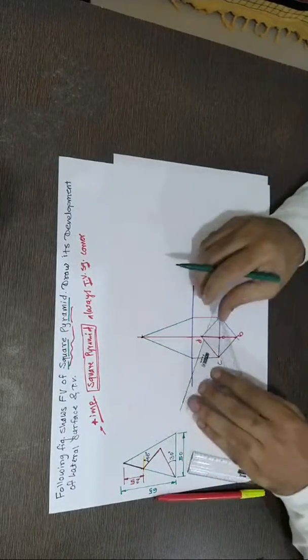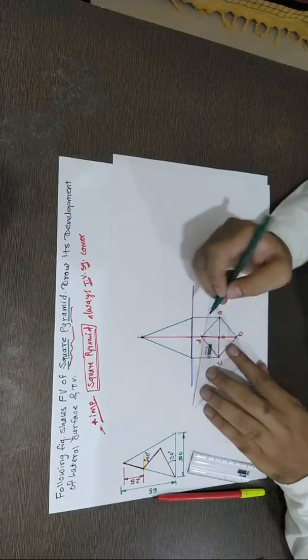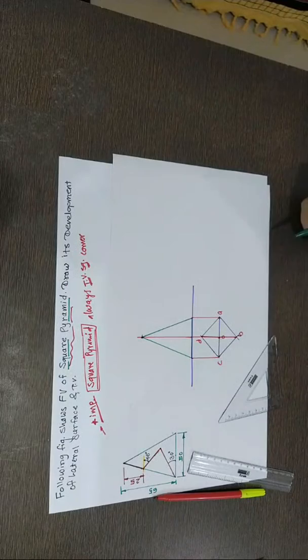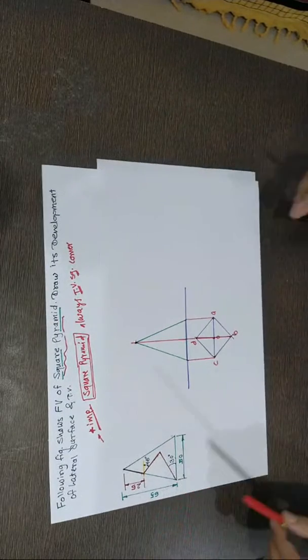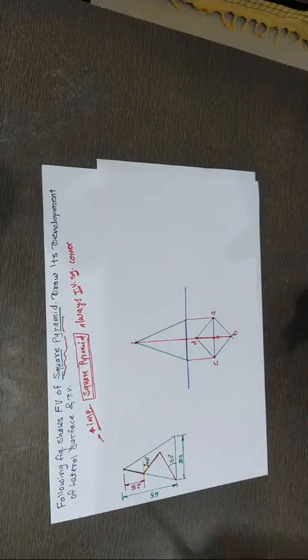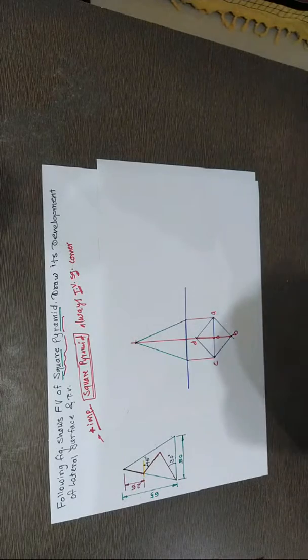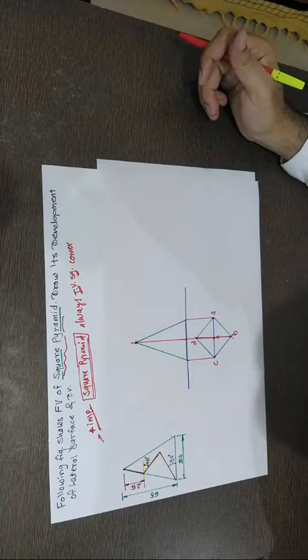So this makes it very easy and it makes the least mistakes. If you draw the square like this, or means resting on a side, there may be chances of mistake. Or you can follow a conventional way of drawing a development for any pyramid. Okay, so that's a very important special case for the square pyramid where you make a mistake many times.